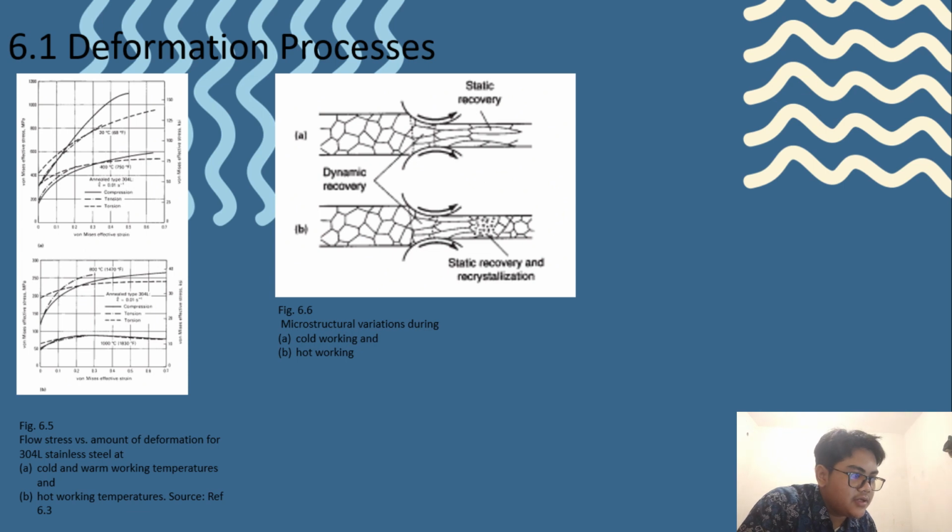One advantage of cold working is strengthening. During cold working, the mobility of dislocations is lowered as they become tangled up in networks and pile up at grain boundaries. This leads to strain hardening, which makes further deformation more difficult to achieve. In figure 6.5, point A, in figure A. At slightly higher warm working temperatures, the degree of strain hardening is reduced, so the flow stress is reduced at higher strains, in figure 6.5, figure A.